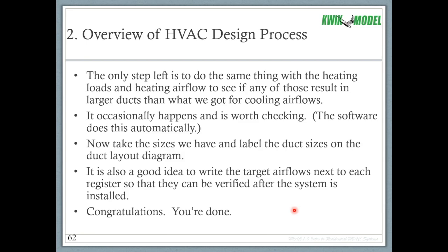Now take the sizes that we've figured out using our table and our airflows and our friction rate, and now label the duct sizes on the duct layout diagram. It's also a good idea, if you can, to write the target airflows next to each register so that they can be verified after the system is installed.